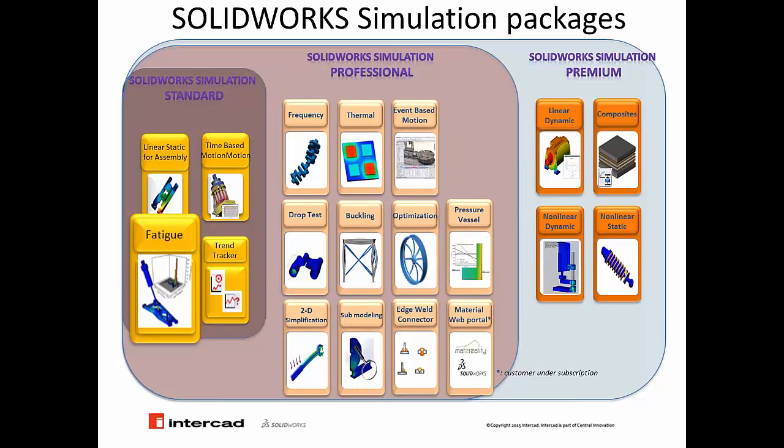And the third level of SolidWorks Simulation is SolidWorks Simulation Premium, where you are able to do linear dynamic studies, non-linear static and dynamic studies, and consider composites. Again, I'm repeating, 2016 will consider linear dynamic studies to be added to your fatigue studies, which was not an option before, and now it's pretty advanced, and you can have dynamic studies and their effect on the fatigue at the same time.